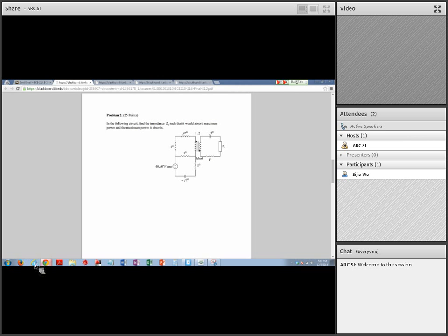Wait, I1 is equal to 0? Yeah, since this is open circuit, which means infinite resistance, you push it down here. Here's an infinite resistance over here. So there's no current through here. By this relation as well. Since I3 cannot flow over there, open circuit, and this relation exists, I1 is also going to be 0.